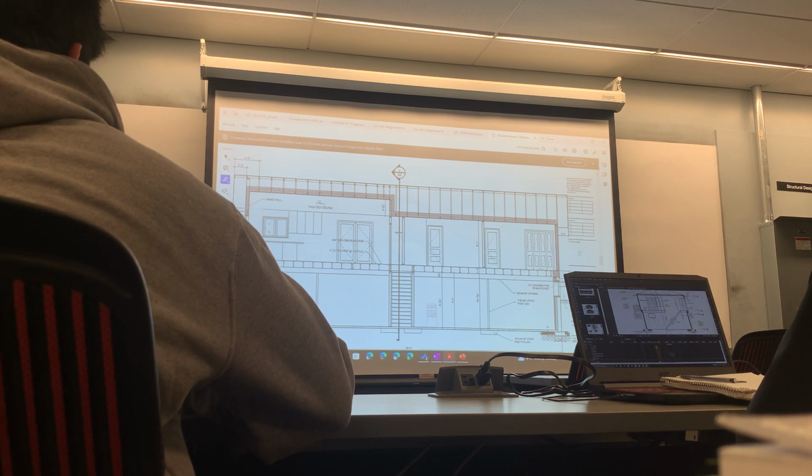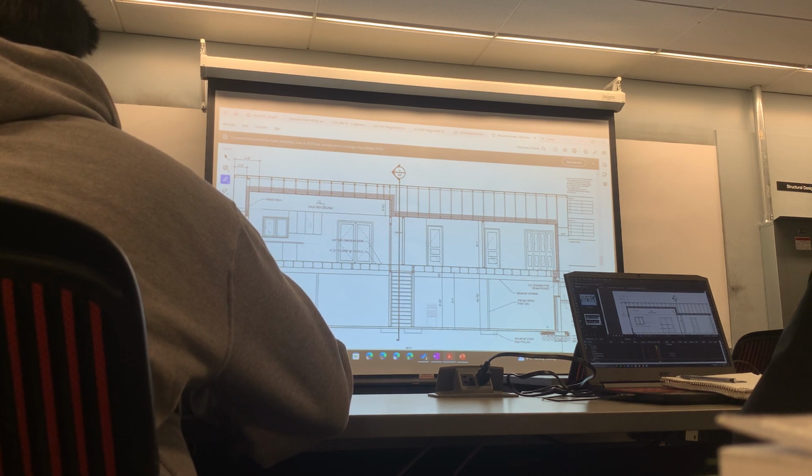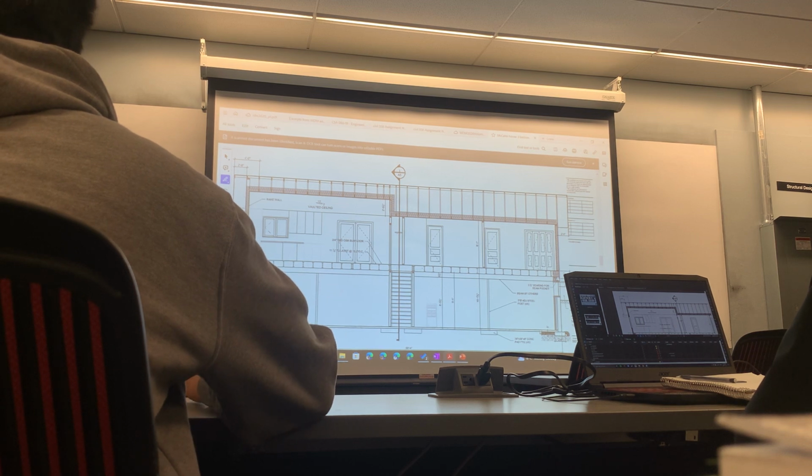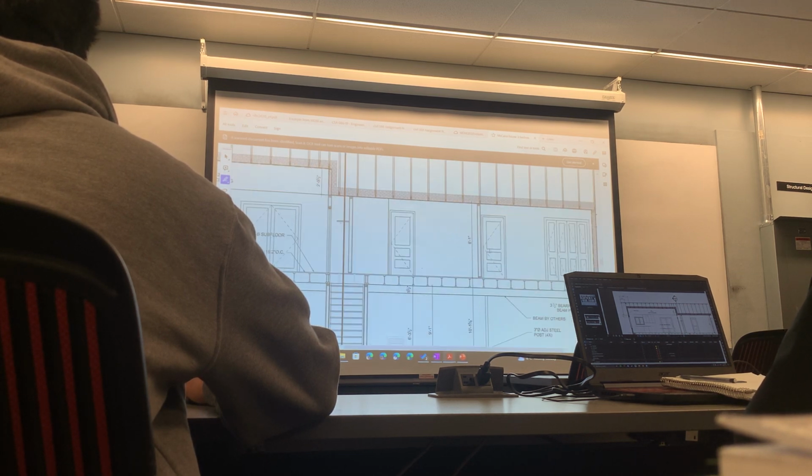The wall's 8 foot here, and then with the vaulted ceiling, look, the trusses get shallower, right? So the interior ceiling height gets higher. What does that do to the wall height? The wall height increases too. So now you've got 8'1" plus 2'9". That's about 10'10". We're still under 11'8", so not quite tall walls.